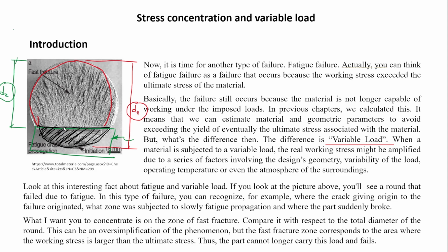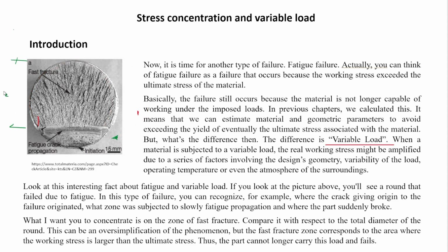And one of the cases is because of this separation of waves or surfaces in the affected area of the part. So you have a very well polished area here, and polished because as this was cracked, meaning that the other part of the shaft separated at this point. So at this point, the relative movement between the two pieces polishes this part here. And then when the part is not able to withstand the load, it just tears up completely. But this part here in the bottom is more or less going to be polished.